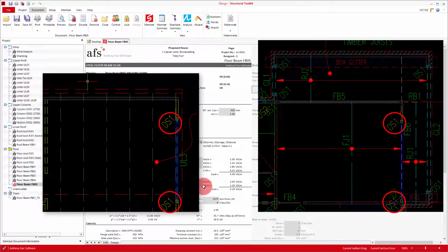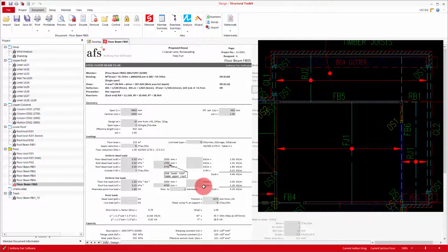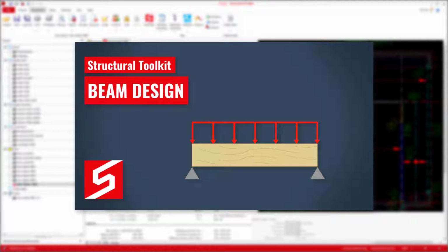When it comes to supporting columns of lintels, you can sometimes justify idealizing their loads into a UDL, but given the spacing of each end column, it probably isn't very appropriate in this case. This kind of design is going to be more suited to a linked analysis member design, where we'll have more options on what we can do with our loads. If you're unfamiliar with this approach, it would be worthwhile to have a look at our beam design video.